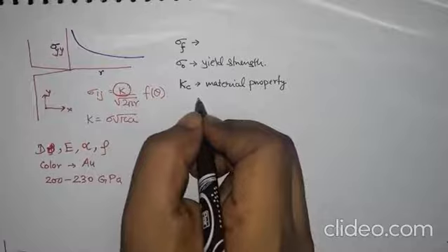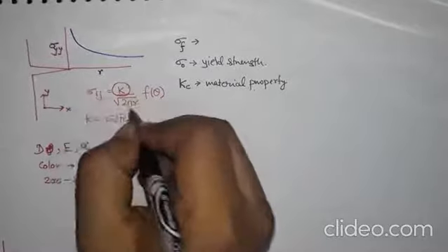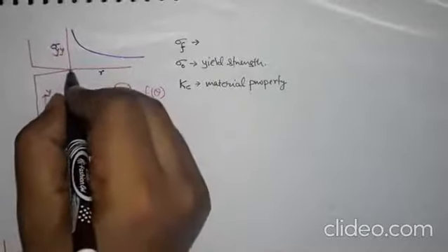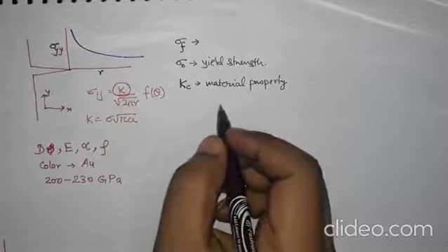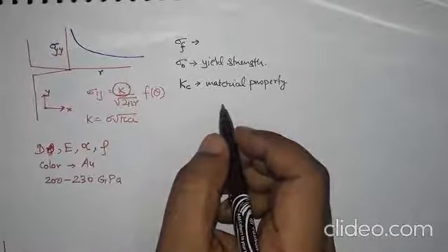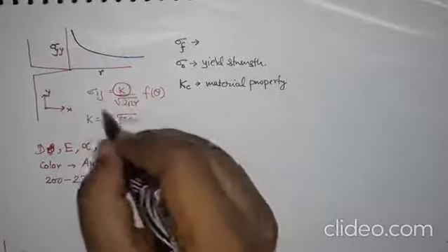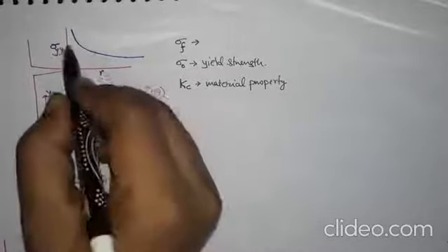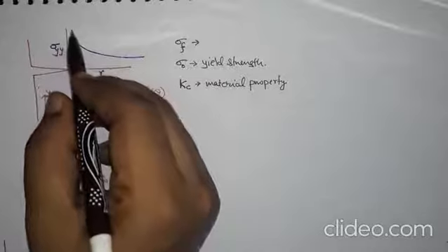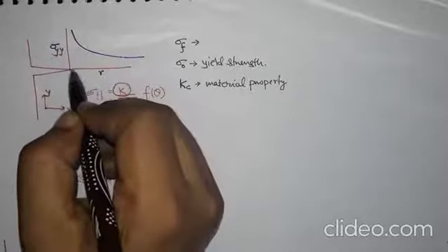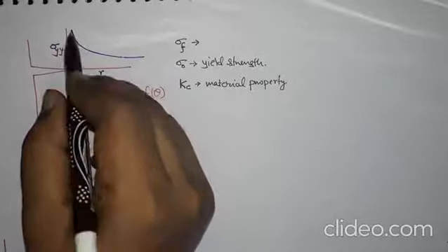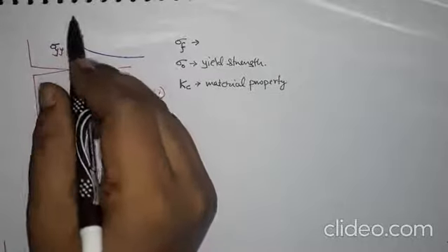But before that, the question is, what is the stress at r equal to 0? So exactly at the tip, do we know anything there? So the answer is the stress according to this equation will be infinity. So it goes asymptotic as it goes closer. So r is going closer to 0, and the stress is going closer to infinity.